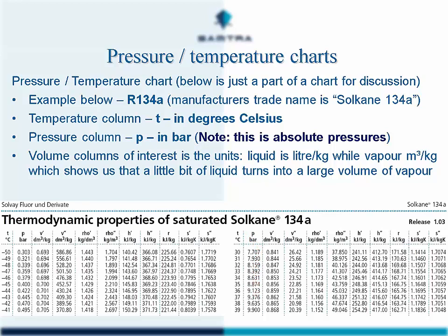Of importance to note is that these are absolute pressures. So the pressures are an absolute value. That means that you cannot take the number you see on a pressure gauge and go to the chart. You have to modify the pressure gauge reading to make it an absolute pressure. We will look at this later on. The rest of the columns are other information that would be used by designers and system installers and so on.